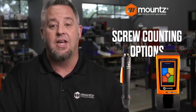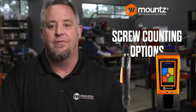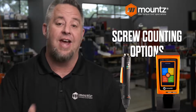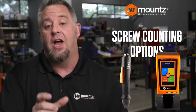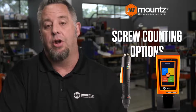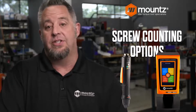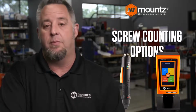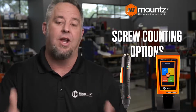And so you'll see that in our example as we look at our demo process for the DC tool. But this one will keep count for each specific fastener set within a specific preset that is being used. And so that count will also be part of the process. And the error proofing aspect of this is, instead of using a time-based system where we create the window of a minimum and a maximum time, the DC tool allows us to actually create an angle window.